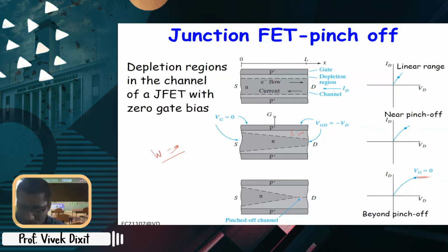Now, what happens beyond pinch off? There is no channel here. So that means it's a depletion region, right? So that means the field is there. There are no carriers to stay in this region, but the carriers can move through this depletion region due to the applied field.